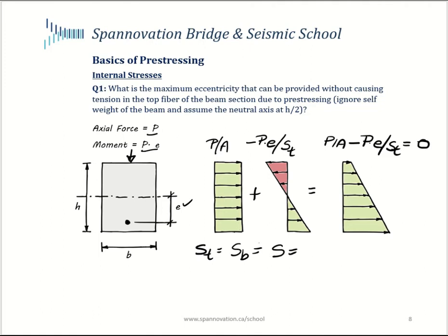And I know that for a rectangular section, it is b, which is the width, times h squared divided by 6. Okay, so you can go check this expression out. You can Google search it or go to any textbook and you should be able to find it. I'm going to use this equation over here. Let me call this equation 1. And I'm going to use the section modulus. Let me just call this 2 and work with these two.